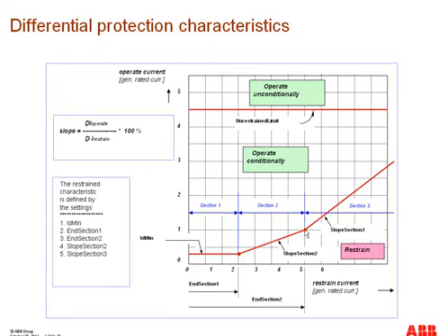Section number 2 covers the more current dependent inaccuracies in the differential protection schemes. And in section 3, the slope will be more pronounced and is designed to result in a higher tolerance to substantially take care of the current transformer saturation at high through-fault currents.